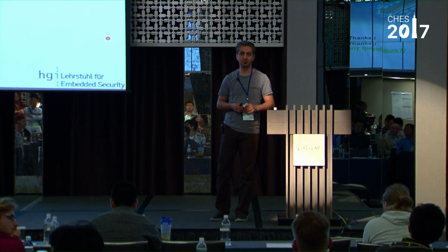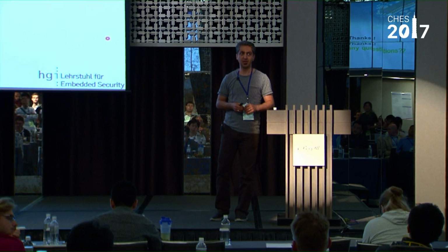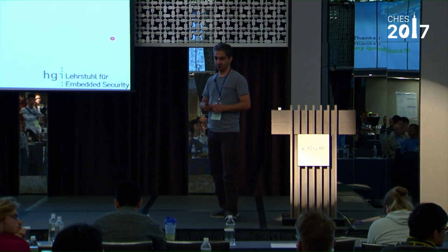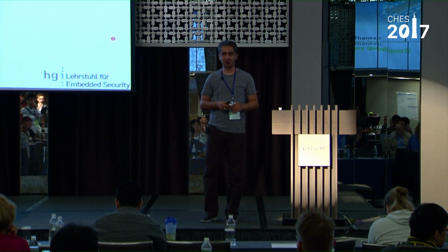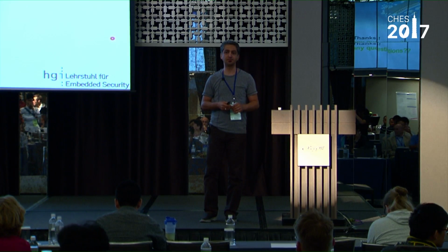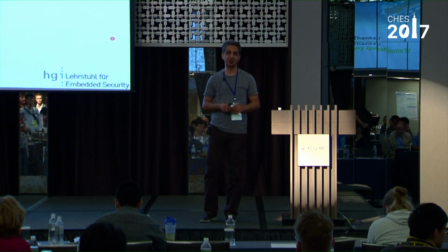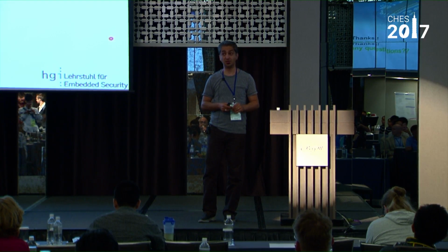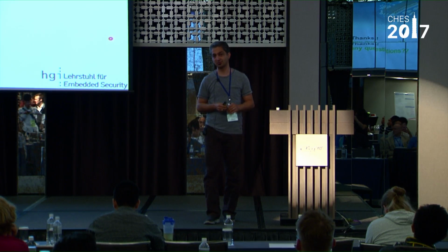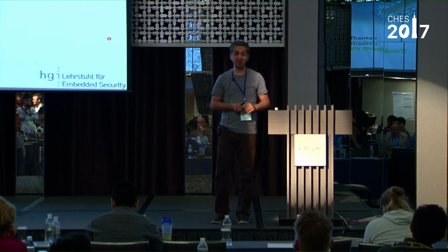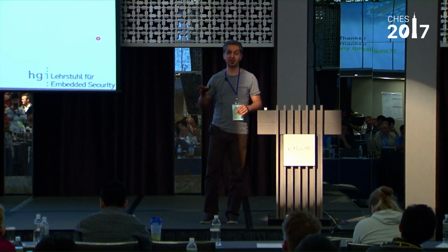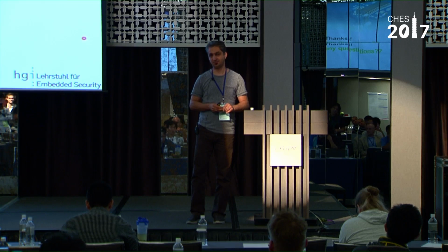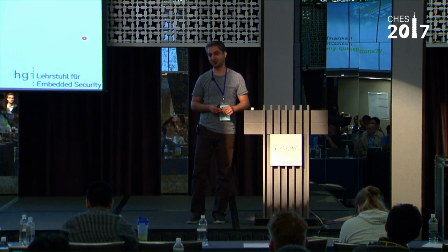Was it synthesized with a placement methodology or just a wire load model? That makes a big difference. This is just synthesized based on the technology library which is given. So you didn't do gate mapping? Gate mapping is done by the synthesizer, yeah. Right, so you map the gates? Map the gates definitely, but placement not, not at the layout level. But what about the wire loads? Did you consider them? No. Usually it's not considered in our community, sorry.